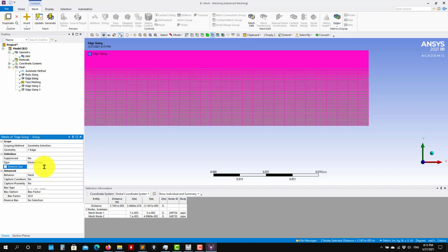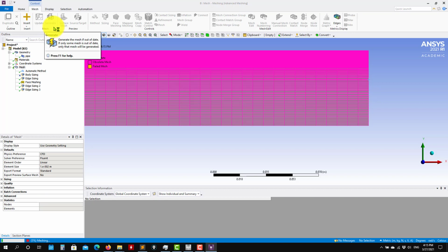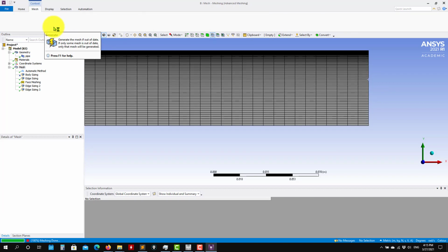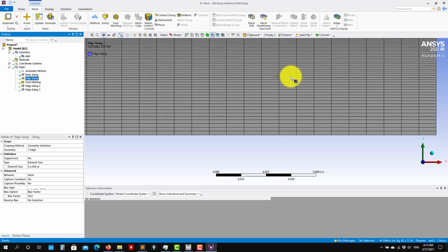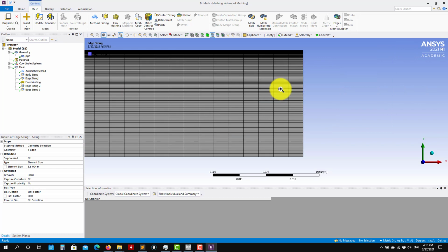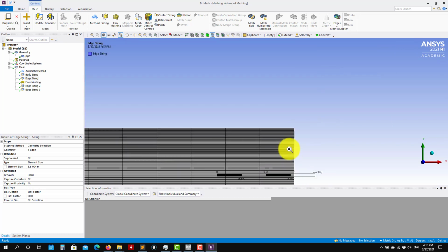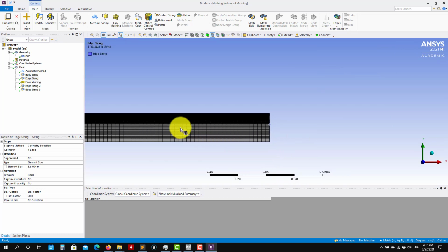Okay, but so this is a little, it's up to you to play with the parameters. Okay, you know how to estimate your distance. Also, you need to keep the cell count within the maximum number of cells that you can use. That is a little bit more than 500,000 cells. Okay, so this is what we have.